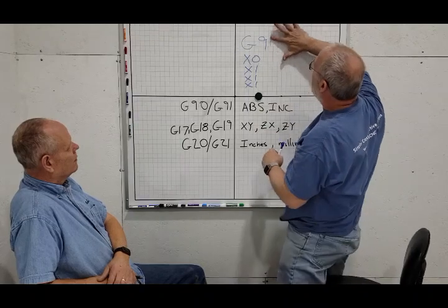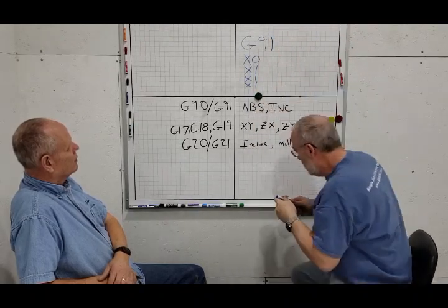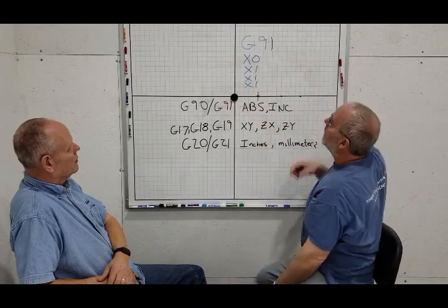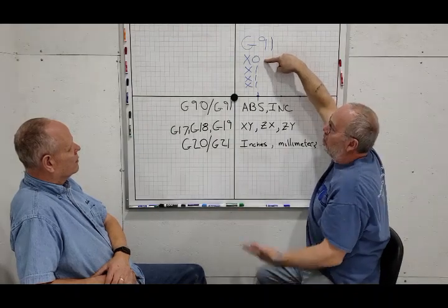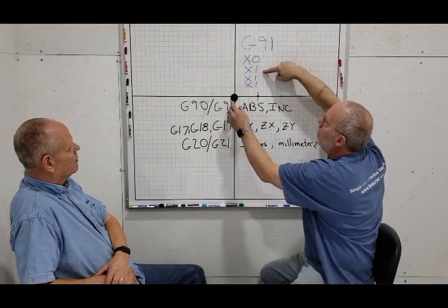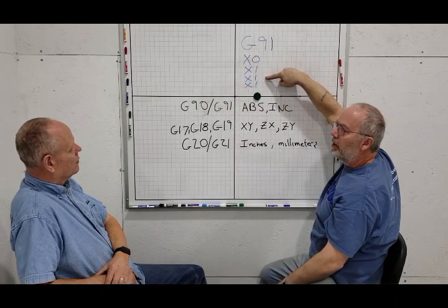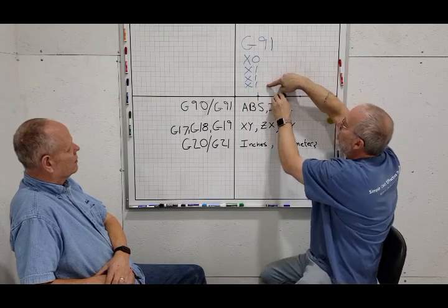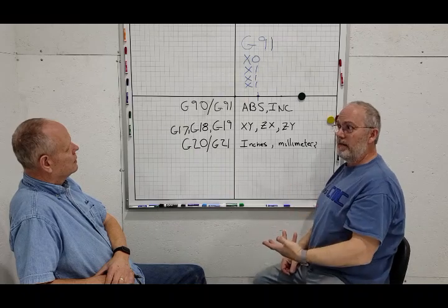Now, all I do now is I take and I say this is G91. We start again. So we'll start at 0. It goes to the first line. It says it's 0, incrementing 0. It's still there. And it says X1. Reads the next line. It says X1. It doesn't stay now. It goes one more. X1. It goes one more. Okay. So that's incrementing values.